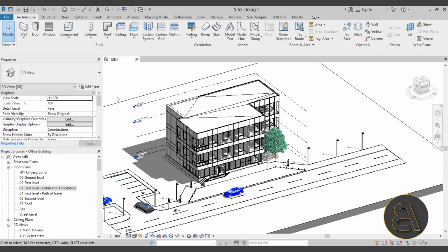Now we're going to be tackling the topic of adjusting the graphics at the project level. So any adjustment that we make like this will affect each view in your project. Now, if you open up a different project, the changes will not apply there, but only to the original project. What's also good about this is if you make any changes that are related to graphics and you send that project to somebody else, those changes will still apply, so that is really important.